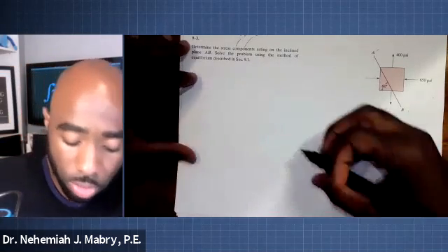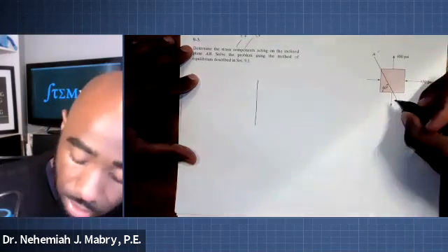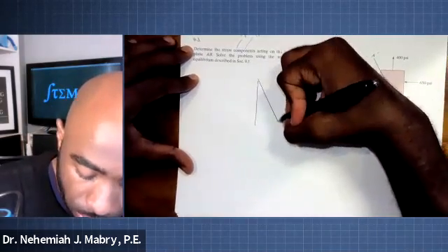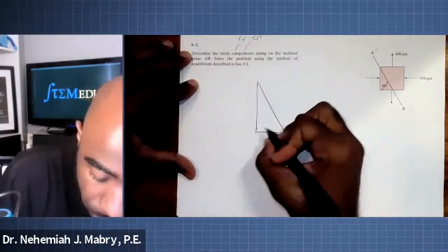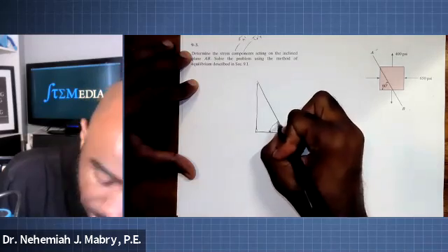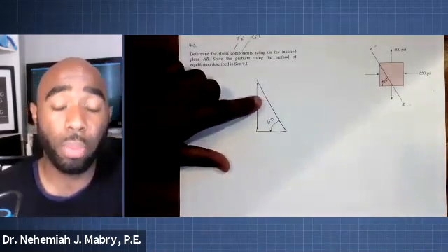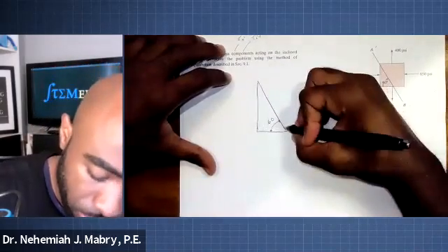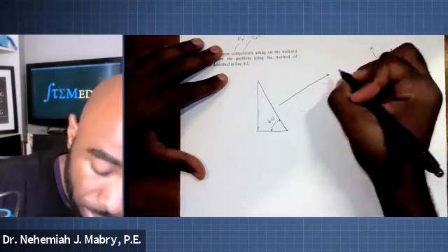So let me go ahead and do what we did last time and draw this triangle as a way to illustrate this orientation of 60 degrees. We're always going to draw perpendicular to this hypotenuse. We're always going to draw that as our new x prime axis.